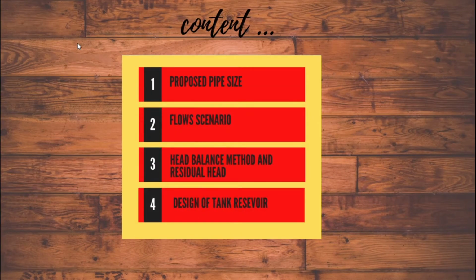For this project, I need to consider the selection of pipe, flow scenario of design flow, the head balance method using the Hazen-Williams equation, analyzing residual head from the reservoir, and propose the design of the water tank reservoir based on the calculations that have been recorded.